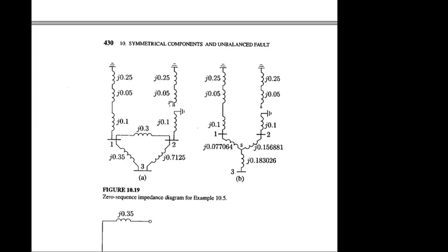Okay, so I understand, sir. Okay. The Y delta position will give you an indication whether it should open or not. So based on that, and it is applicable for only the zero sequence circuit, not for positive, not for negative, only for the zero sequence circuit. Okay, you have to be careful about that. If it has any delta, you have to draw the circuit accordingly based on the zero sequence transformer equivalent circuit.